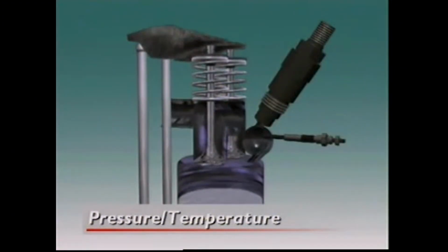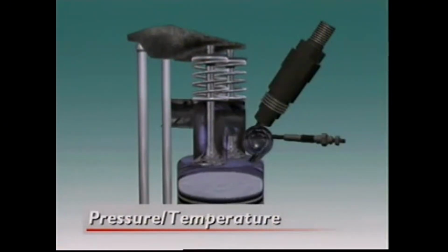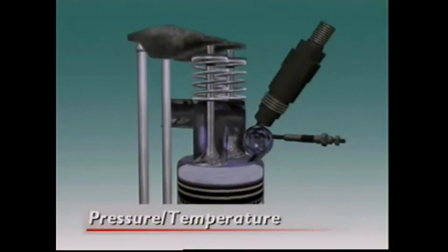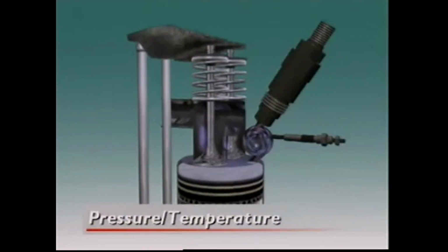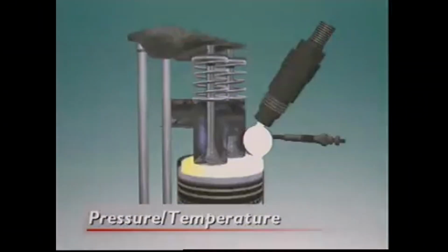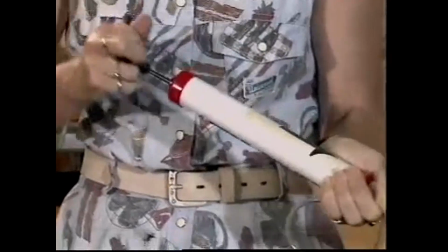This is put to use in compression ignition or diesel engines. Air in the combustion chamber is highly compressed by the piston. This causes such a large rise in air temperature that when fuel is sprayed into it, the mixture ignites.